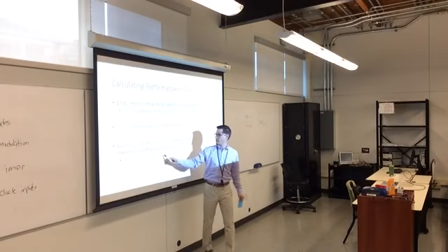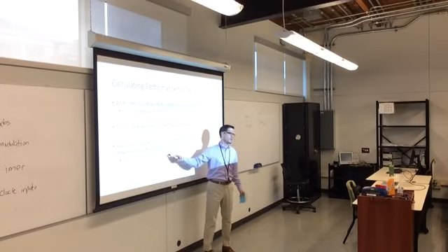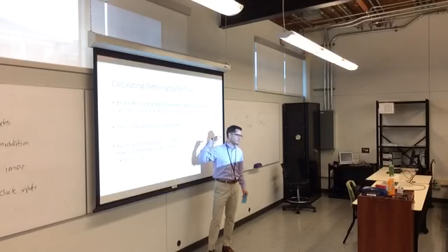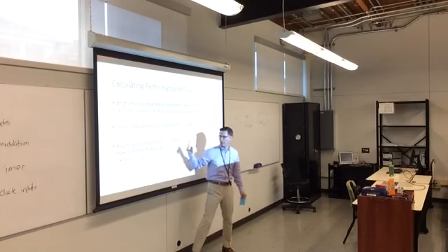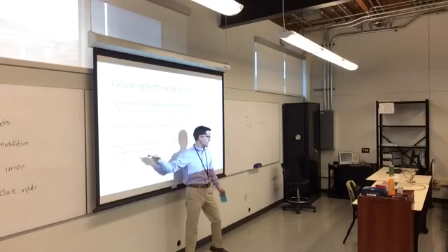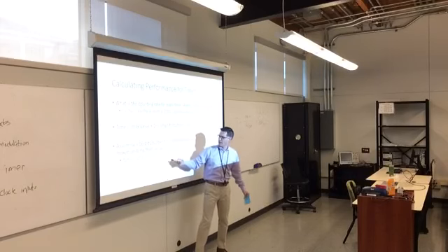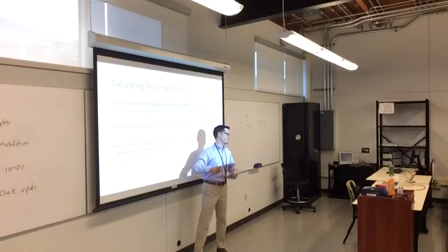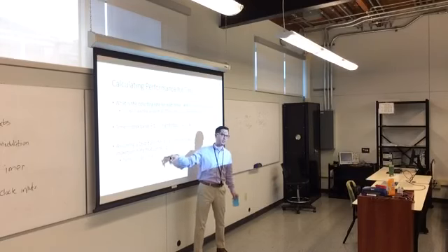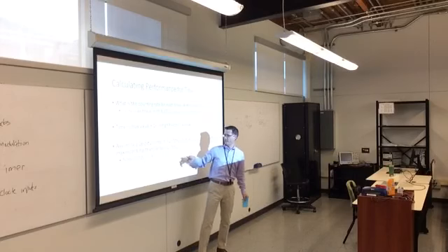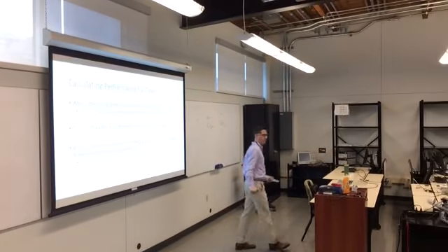25 million. The way you want to think about the frequency, I think Michael asked us this in seconds, and that's actually a pretty good question. Because this is unitless, it's just a number. This you want to think of as 25 million things per second. So this is the only thing that actually contains a unit. Divide that by 512, you get roughly 1.34 seconds.